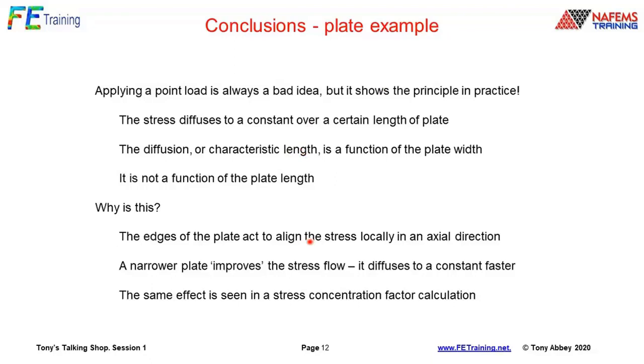If I've got a very big wind tunnel and a small feature in there, then the air comes up to that feature and has to diffuse around it or move around it in quite an abrupt way. If I have a narrow wind tunnel, or the object is occupying a large amount of space, then the flow is entrained along the walls of the wind tunnel. So it's not a surprise. The flow is already moving parallel, and then it sees the object and changes its direction a little bit. That's why putting a large object in a narrow wind tunnel isn't a good idea, because you're not modeling free stream flow.